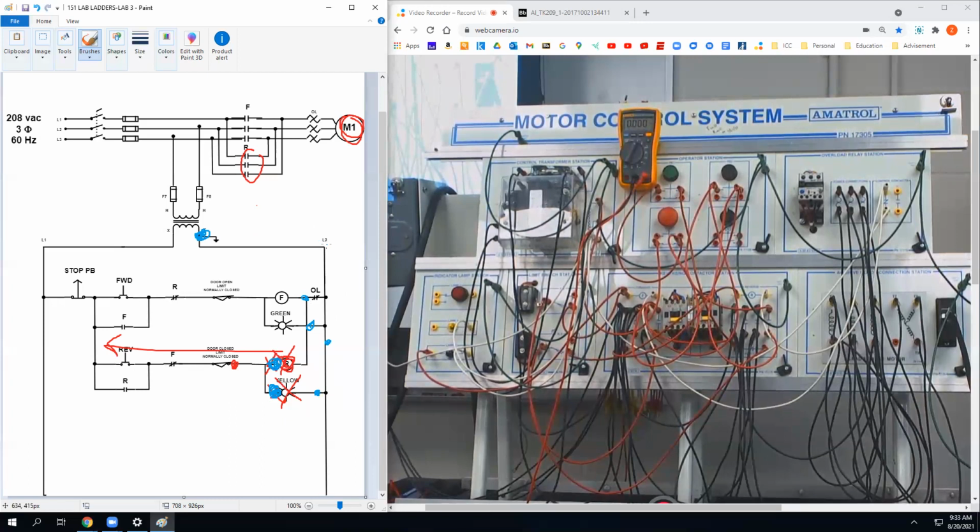Yeah, but if you got a break in this wire, you're going to get really confused. Since our transformer is sitting right there, the best source for your negative lead is right here on this X3. Make sense?